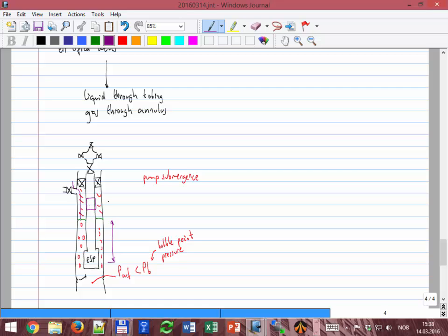It's something that allows passage through the annulus, but it's also protected, and also has a hydraulic line. If something fails up there, it's going to close. It's going to go to the fail-safe close position. So it's called an annular safety valve, I think.